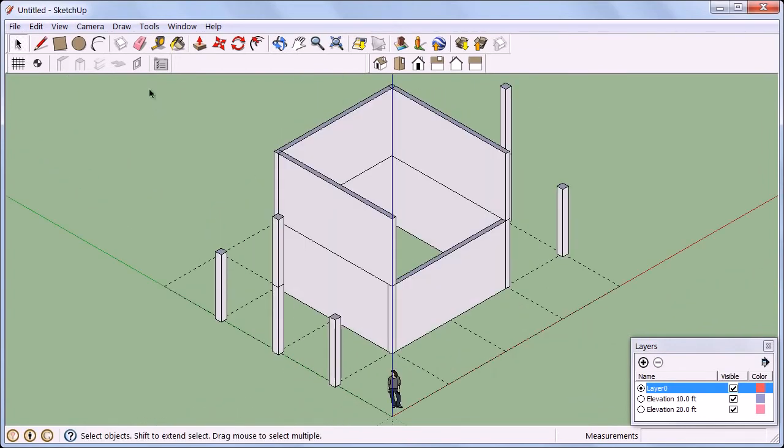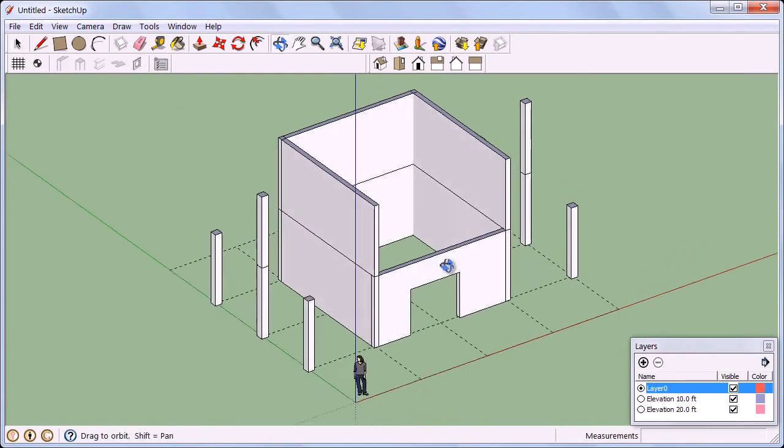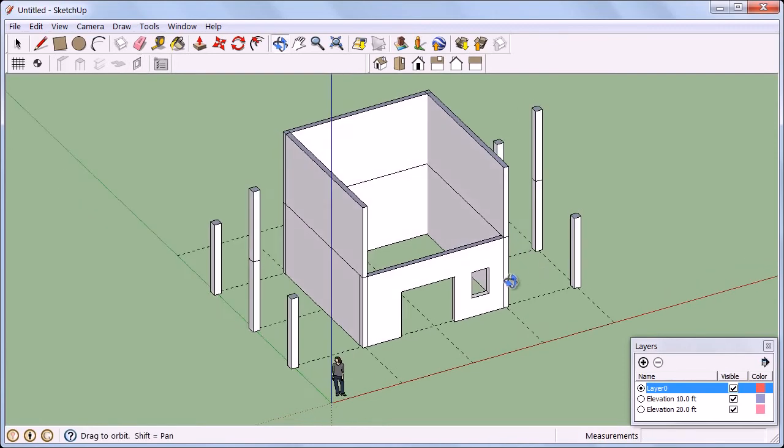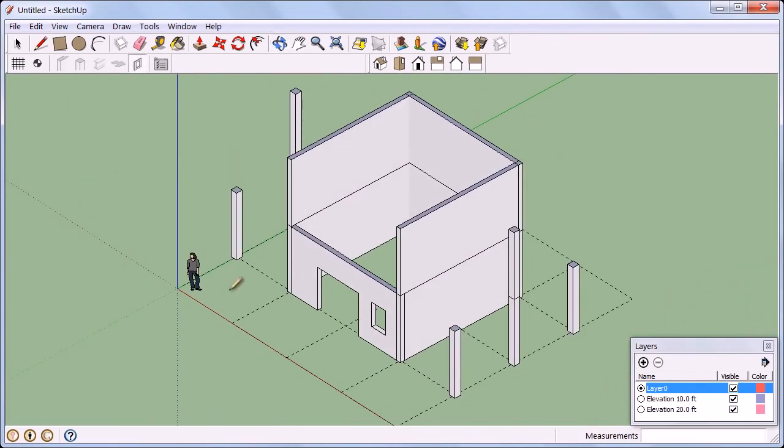One last tip. Openings on wall elements can be drawn only in 3D mode. So you will always need to switch back to layer 0 before adding openings for doors and windows. Also, if required, openings can be accurately positioned using input from the keyboard.